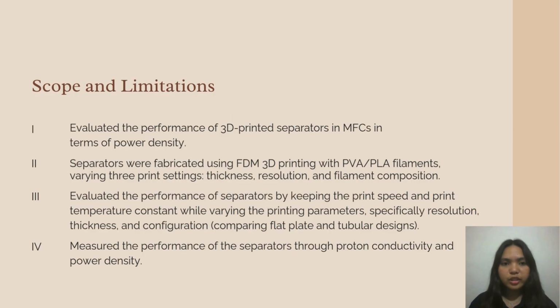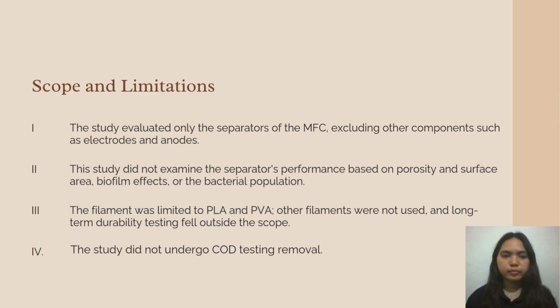Scopes and limitations. The study assessed the performance of 3D printed PVA PLA separators in MFCs, focusing on power density. It examined the impact of thickness, resolution, filament composition, and configuration while maintaining consistent print speed and temperature. Performance was evaluated through proton conductivity and power density, highlighting the influence of printing parameters on MFC efficiency.